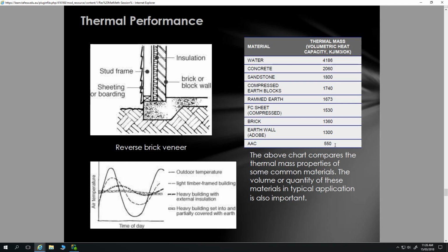And then also, once you put that thermal mass on the outside of a building, that thermal mass doesn't give you much of the thermal flywheel effect for the building in the morning. So a material that has its virtues doesn't work well as an external wall because of its insulation, and then you're not also utilising its virtue of thermal mass.